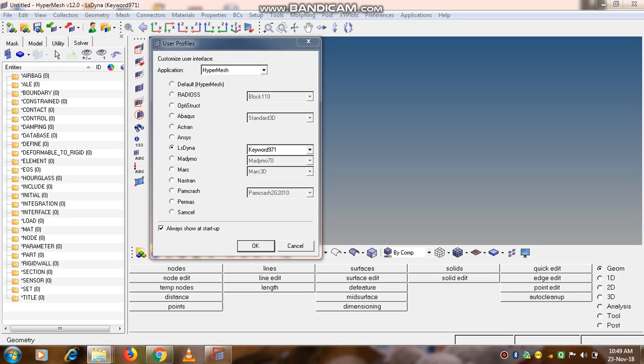to convert an infinite number of degrees of freedom into a finite number of degrees of freedom. Now why are these infinite degrees of freedom there? Because if any object is there, how many points will it have? Infinite points. So for an infinite number of points there will be an infinite number of degrees of freedom. So it will be difficult to calculate the amount of force or the deformation produced at each of the points.